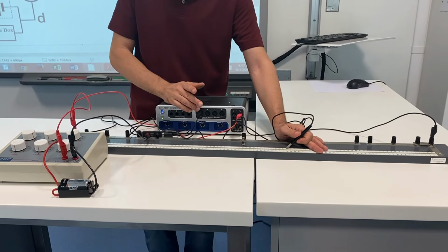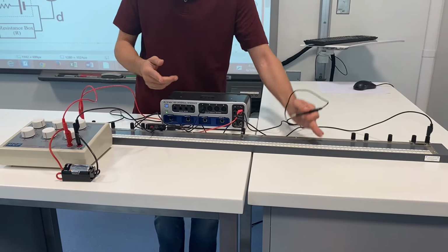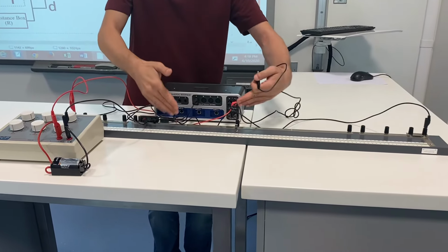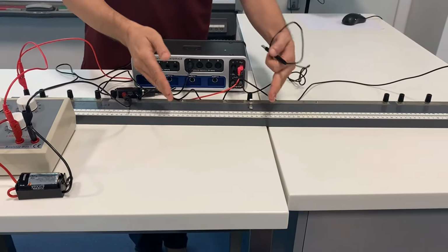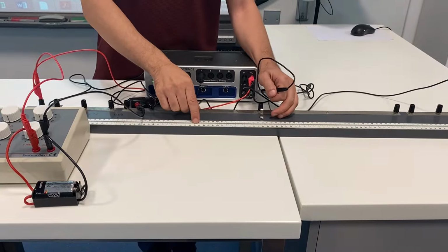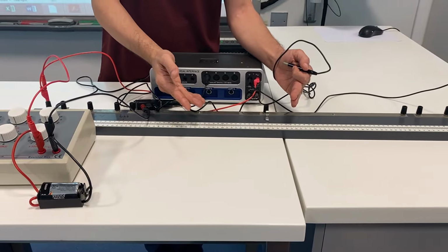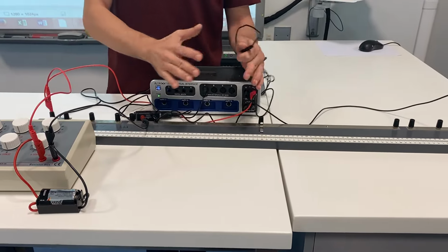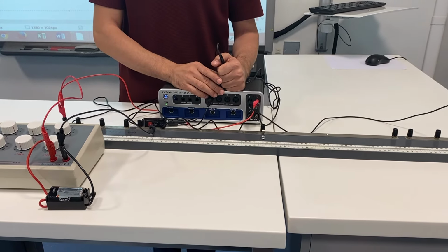Because remember, otherwise you start having errors because of this problem. And there is also another problem, which is this wire is connected to 2 volts all the time. So it's going to heat up, and also you'll notice that if you leave it for a long time, because of heat, the length of the wire increases as well. Okay. So to prevent all of this, you have to take your readings quickly in the way I just demonstrated.